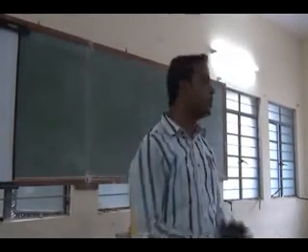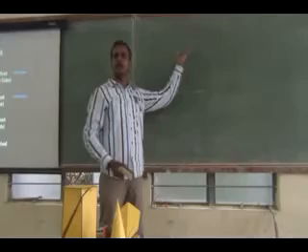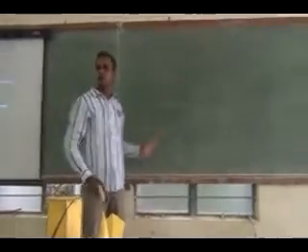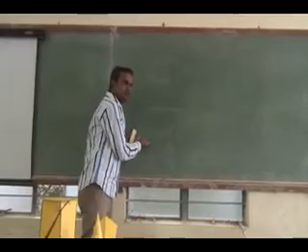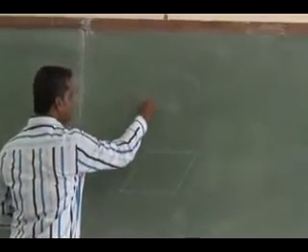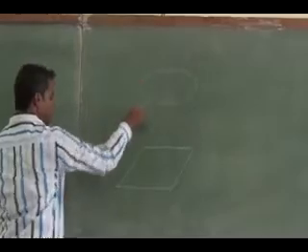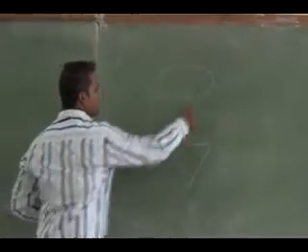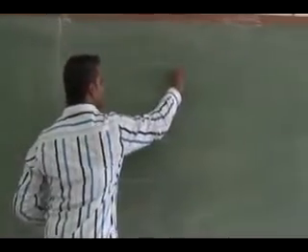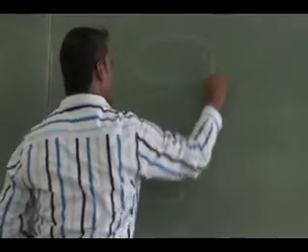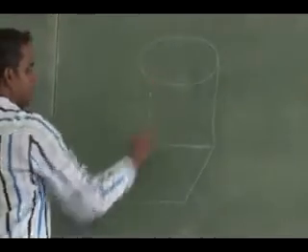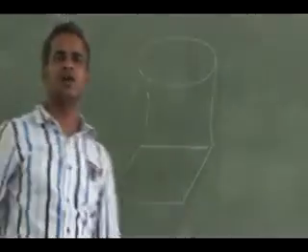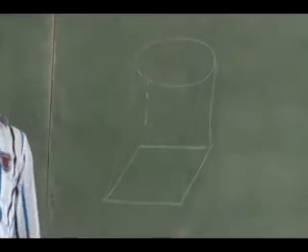You see here, the triangulation method. In triangulation, one end face is a square and another end face is a circle. So the solid is transformed from a square to a circle. It will be something like this. It will be transformed in an irregular manner, right? So how can I develop this kind of solid using the triangulation method?